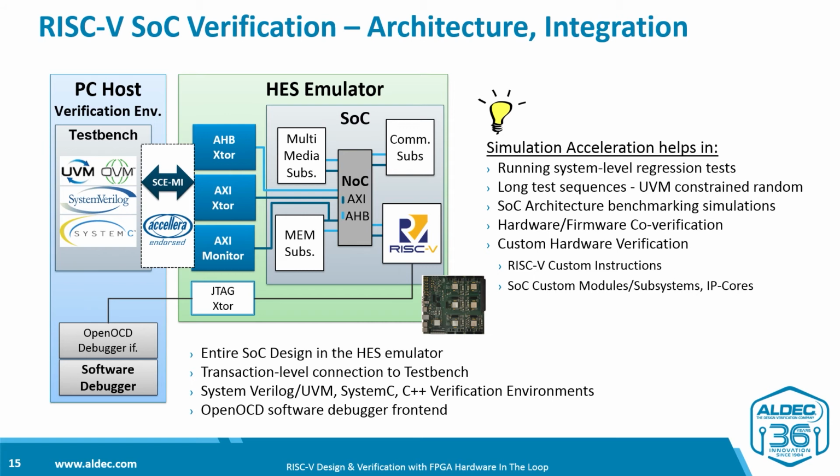Next, the SoC emulation, if it passed all the regression tests, becomes a hardware platform for software developers. If the emulation was built with a JTAG interface transactor, the processor can now be controlled from any software debugger. For example, the popular OpenOCD debugger interface can be used to enable a GDB debugger connection.